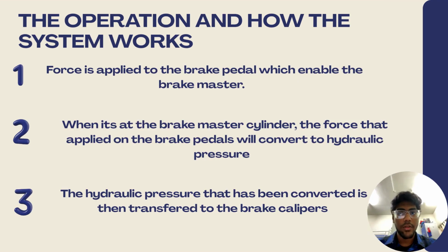Now I'm going to show you the operation and how the system works. First, a force is applied to the brake pedal, which engages the brake master cylinder. At the brake master cylinder, the force applied on the brake pedal is converted to hydraulic pressure. The hydraulic pressure is then transferred to the brake calipers.